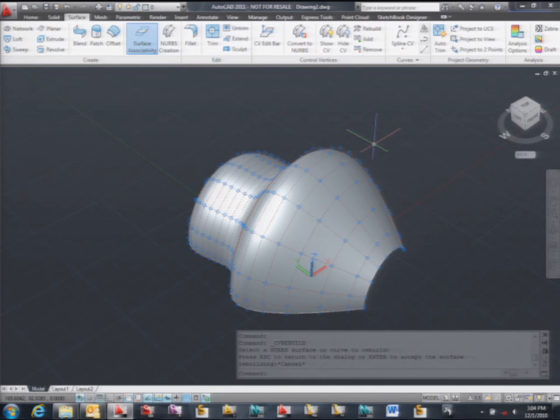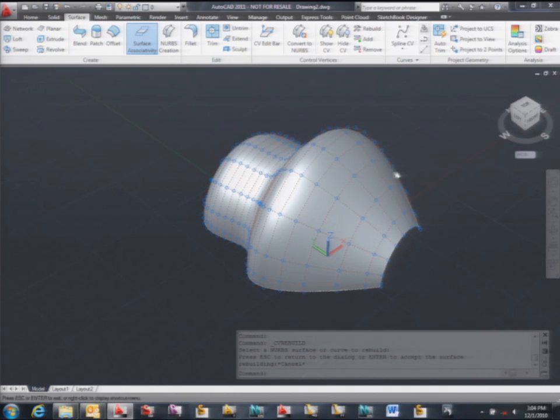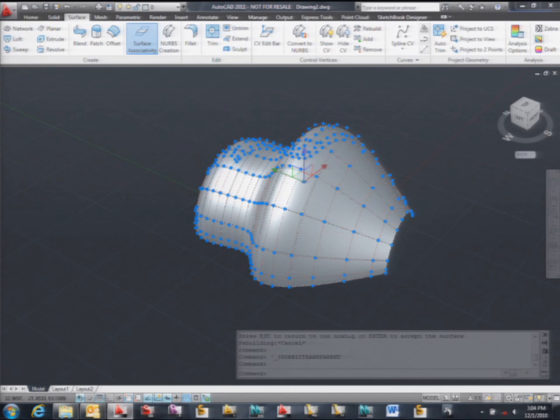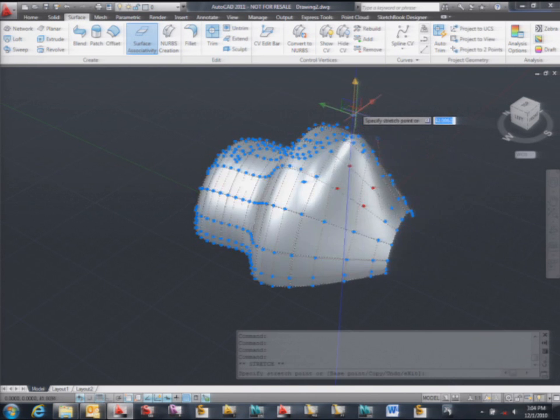Okay, so this is what we call the hull, right? The hull is that kind of extra frame of control vertices in both directions. And now, what can we do with the hull? We can do whatever we want. That's the whole point, and that's the nice thing about NURBS. So I could select specific points of the hull, and if you want to select more than one, you just go with Shift, and all the points that you selected will get hot grips, right? And then, for example, you just want to move these guys up, right?